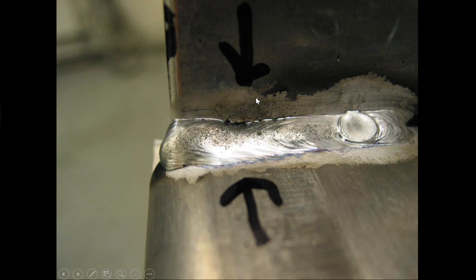Now, I just want to point out, when you see that black like that, there's a couple of points. First point, you can't weld that. That oxide is so hard, you don't even have the capability with your TIG torch of getting oxide, after it's formed, hot enough to melt. And if you did, it would not melt back into the aluminum. It cannot be just added to when it comes to seeing a visual chunk of oxide in front of you.